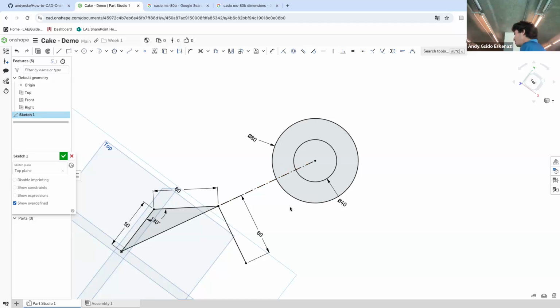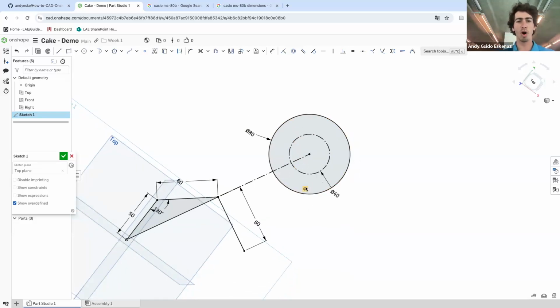And the dashed line means that, yes, I have this little triangle in here and the circles over there. And I can do the same thing with this circle. Click on the circle, then on construction, it becomes dashed. So it's just like a reference. Because when we start giving volume to this stuff, and you'll see it in a moment, because it's extrusion, I make them into prisms. You'll see that it has to be a fully solid line. When it's dashed, it wouldn't work. So I'll start illustrating some of those things in just a moment.